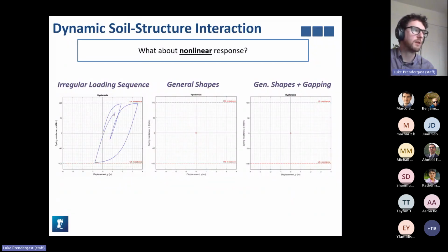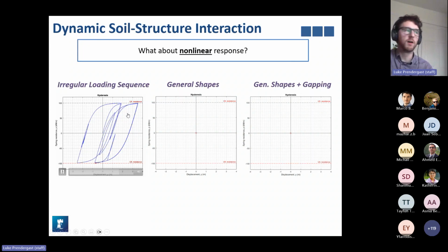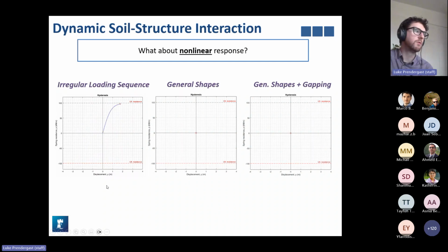This is work that's undertaken, as I mentioned, by PhD candidate Jack Todd-Buswell, which he's recently submitted for his PhD. And it just gives an idea of being able to track the strongly nonlinear soil structure interaction response across a range of values. So the idea is that your PY response is an ultimate resistance, and as the system oscillates within that sphere, it'll oscillate between these bounds across a variety of strain levels. The response here is simulated using a Masing rules type framework. So you keep a record of all of the reversals, and there are a series of bookkeeping rules that are used in this case.